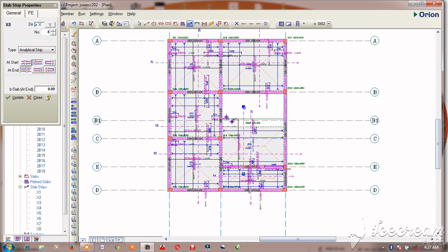So my depth is sufficient. I want to design this horizontal axis as well. It's continuous here, but it's discontinuous here. So I want to design this axis as well. Click it here and hold your control key, then leave it here. So the section is okay.